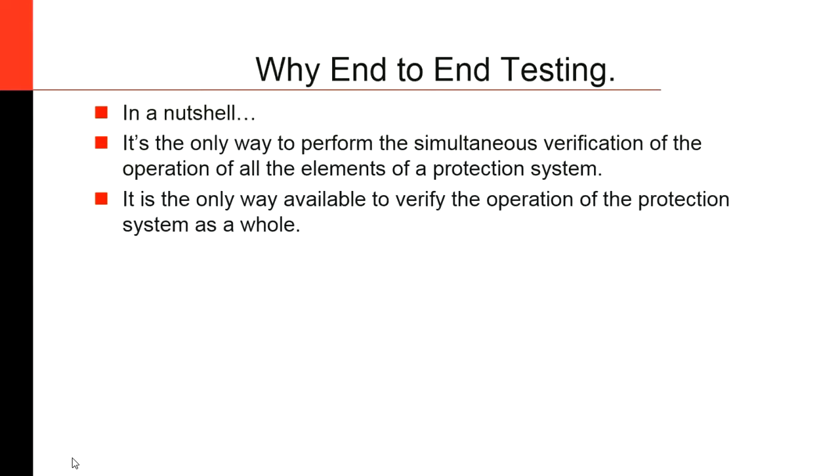Now, why do you do end-to-end testing? Well, we already talked about it, but it's the only way to perform the simultaneous verification of the operation of all the elements of a protection system. There is no other way to verify the actual operation.